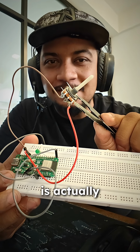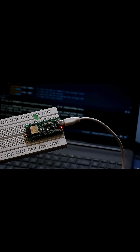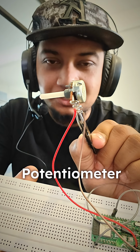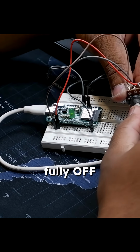This tiny knob is actually controlling the brightness of the LED. But what's actually happening here? See, in the last video we only had high and low, on and off. But real life isn't just on or off. This is a potentiometer, and this lets us create values between fully on and fully off.